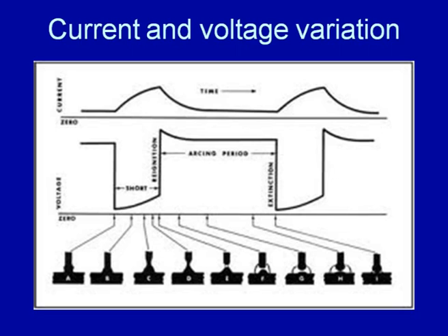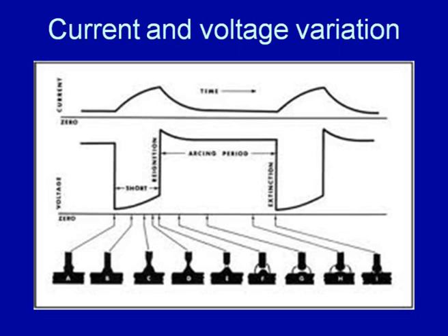In this portion of the time during the welding, the current magnitude also reduces as soon as the molten metal drop is detached. Short circuiting is stopped at this stage, and the welding current starts to decrease. In this portion again the molten metal drop starts to grow gradually, and then short circuiting again takes place.